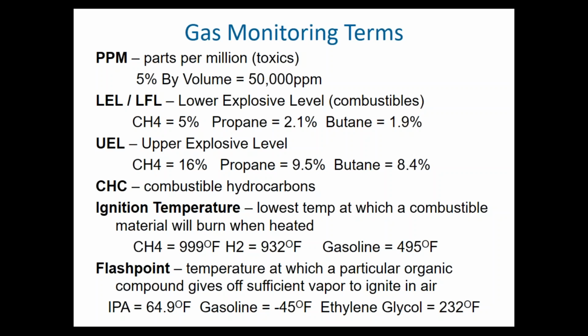Moving on, we always see the acronym CHC, and in our industry that's considered combustible hydrocarbon. Now, when we start getting into actual chemicals, it's important to understand certain properties about those chemicals, because that's going to tell you a lot of information on where you're going to put the sensor, why you're going to put a sensor, whether you even need a sensor.